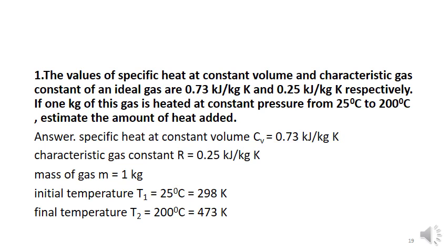Whereas in the constant pressure process, the heat energy supplied at constant pressure is equal to the change in enthalpy, denoted with capital H, so H2 minus H1 is equal to mCp (T2 minus T1). Otherwise, if the heat is rejected, the work done becomes W is equal to minus PdV.